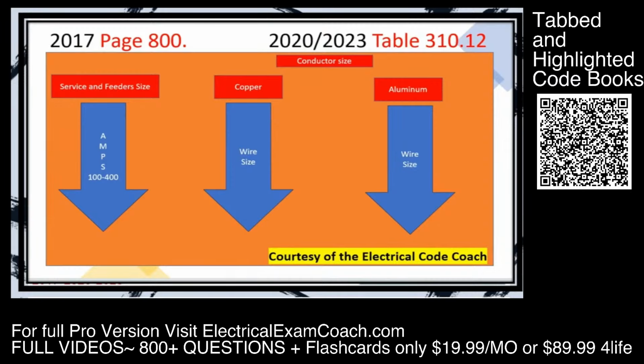On the left-hand side, we're going to find the size of the service and feeder, and this is listed in amps. You'll notice that it only goes to 400 because the rules that we're learning right now only apply to services and feeders that feed the entire dwelling between 1 and 400 amps. And I've got a great graphic illustration in the next slide to show you when it does and does not apply. On the next column over, we're going to see the copper side if we decide to use copper, and then aluminum if you decide to use aluminum.